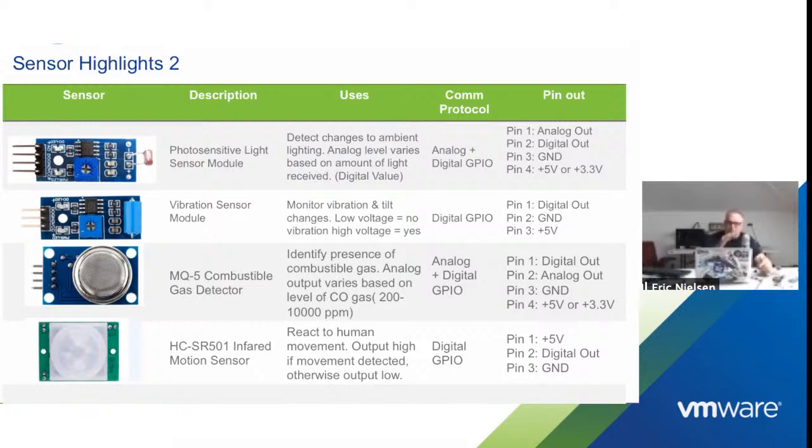Analog can be very precise because you just get a voltage number and it gives you what that number is, versus digital, where if it's a 4-bit number, you can only have a limited number of combinations of an answer. An 8-bit number would do 256, but an analog will give you 1,000 points between 0 and the voltage. So some of these sensors will give you both analog or digital. The Raspberry Pi would normally convert it to digital so that you could do something with it while programming, but it doesn't have an analog-to-digital converter.